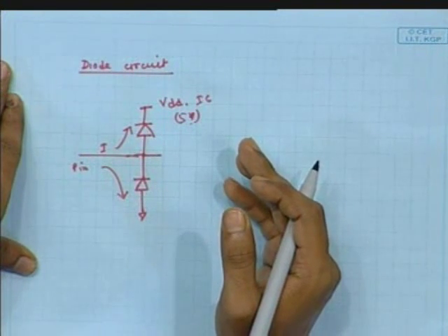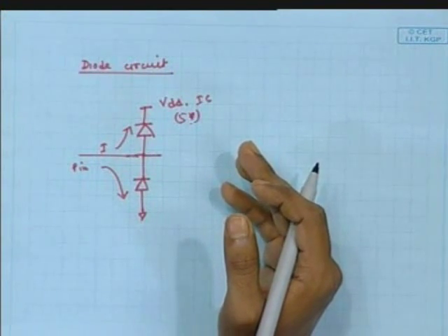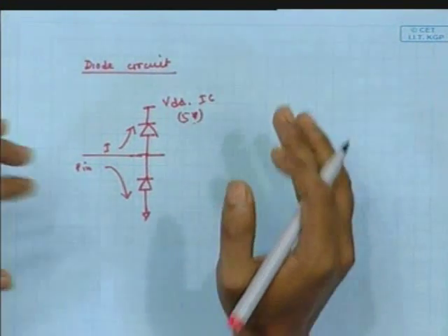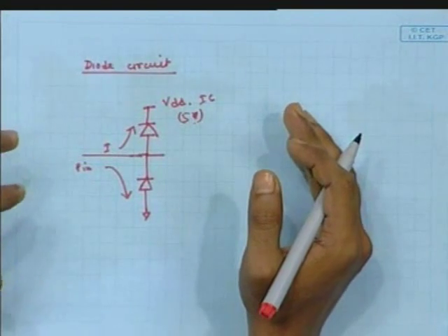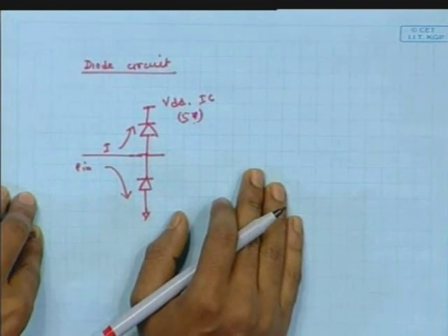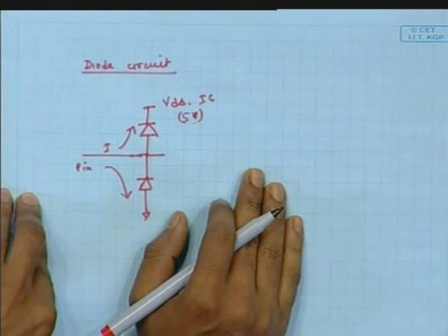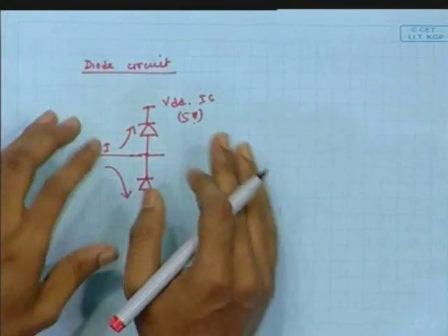So that is limiting. For high frequency circuits, ESD is very critical, because if you use more area, that will help ESD-wise, but the frequency of operation will reduce. That is a trade-off. So for high frequency, you have to take care of the ESD; this is very critical. These are simple ESD diodes.